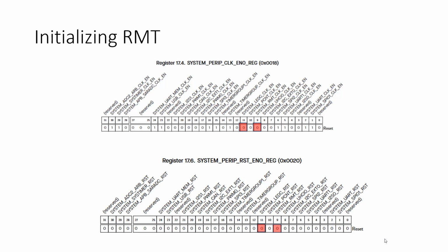They're relative to a base address that has these registers in it, which is called the system space or system base. So there's a system base address, which you can look up in the manual, and then what you're doing here is adding 18 and 20 in hex to that system base address in order to get the absolute address of these two peripherals.